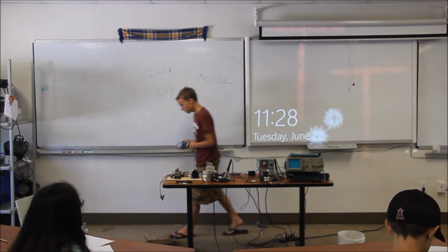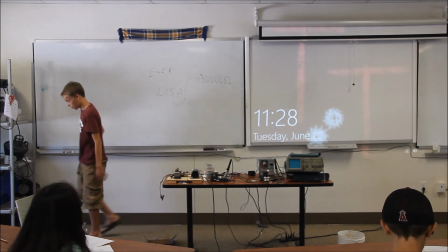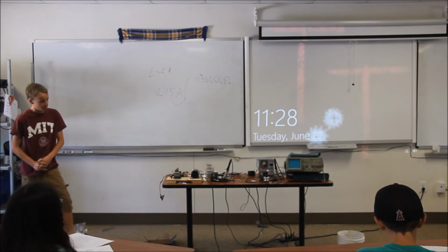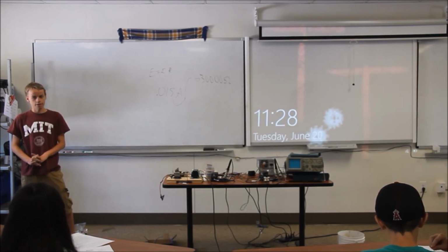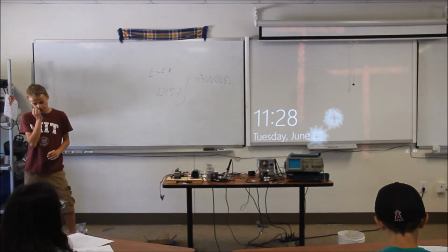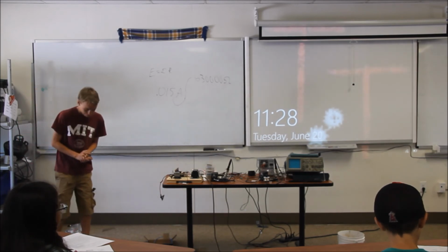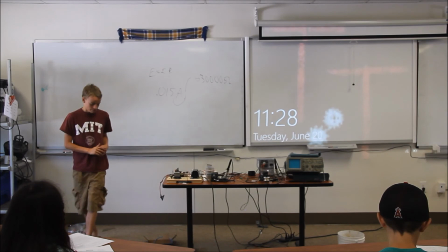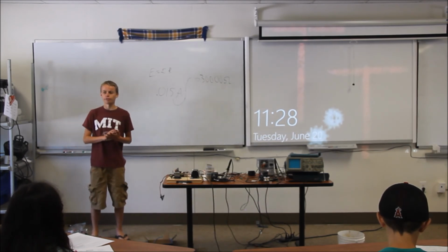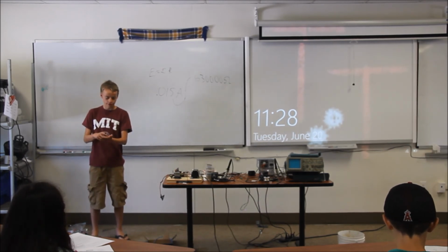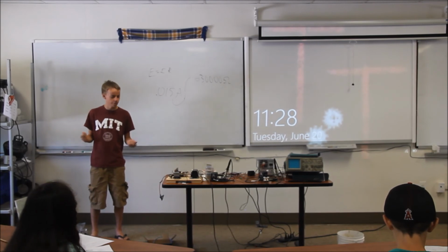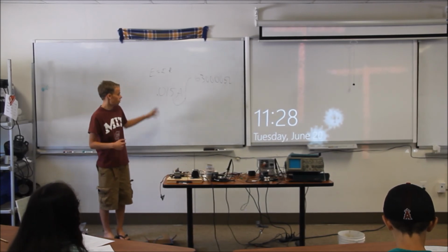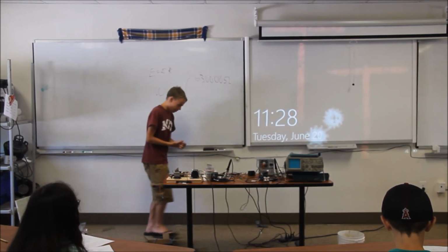It would be really far down, almost close to 100 volts. So you can see that voltage doesn't always mean that you will get electrocuted, because people's skin can have varying resistances based on where their skin is being subjected to the electrical charge and where that charge is happening.